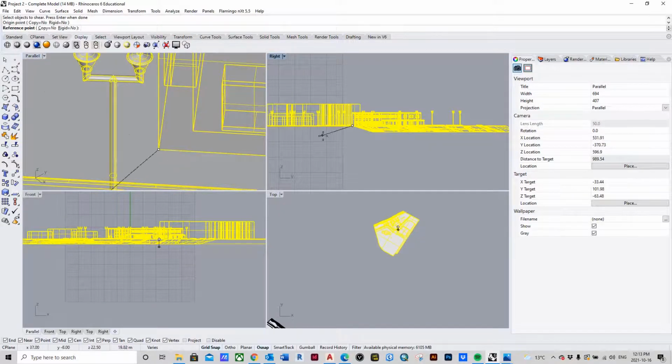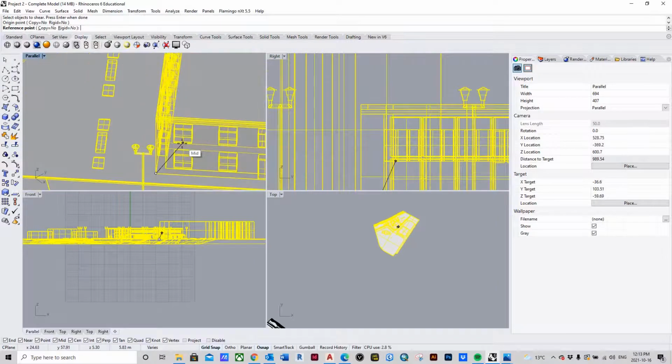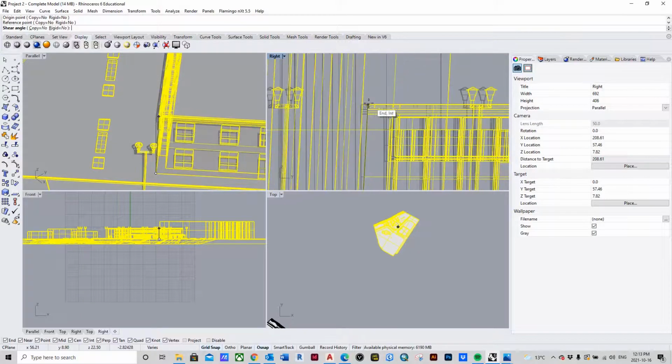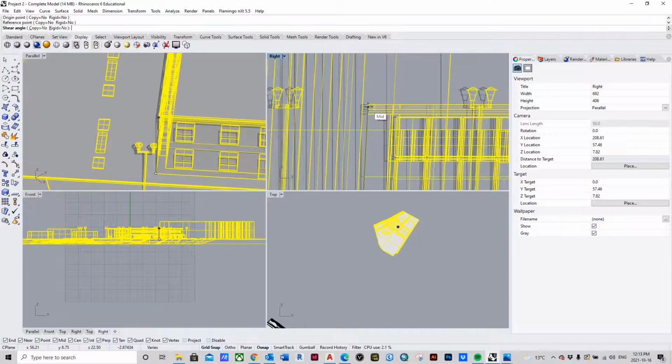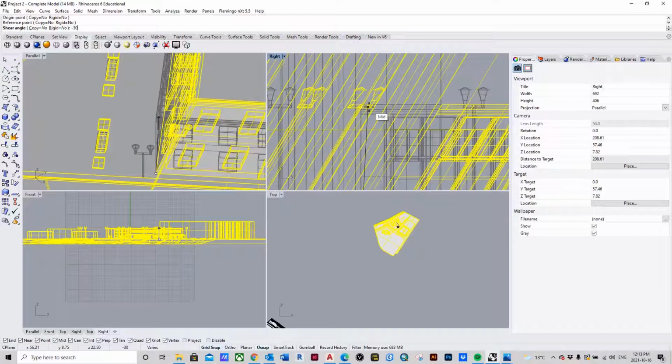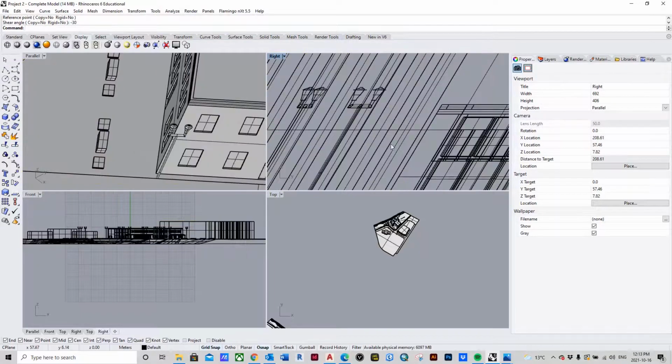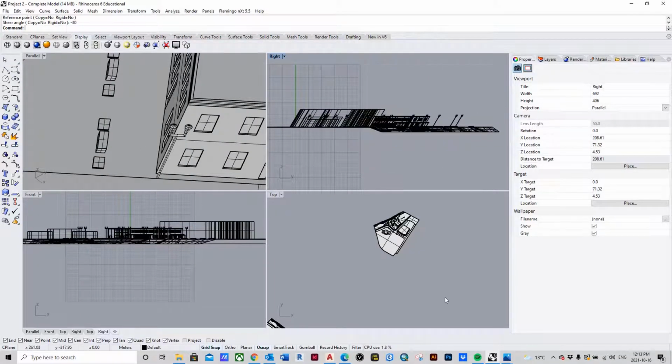So we'll grab that corner, then we'll zoom out a little so we can see that our cursor is going where we want it to. We're going to grab the top of this corner, the part that we're going to be shearing away, and then you can see it shear like that. Once we're in the right view, we have all the shearing direction power and everything. That's when we're going to type negative, we'll just say 30. Hit enter, and wow, it looks crazy in this view, but this view is exactly what we want.